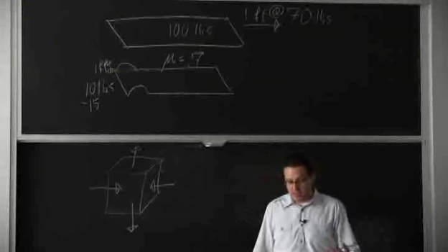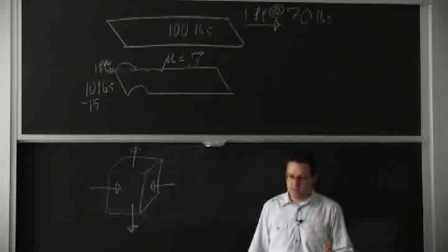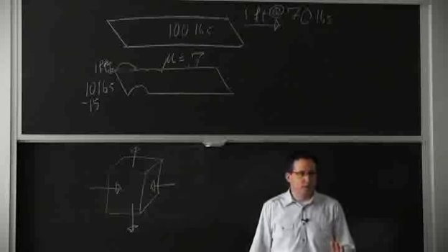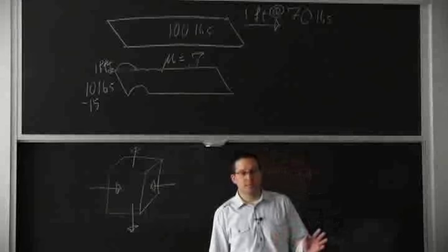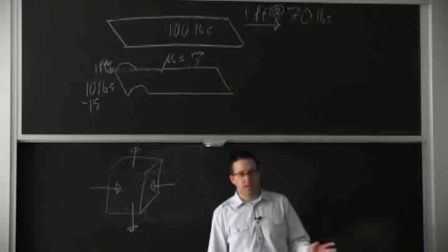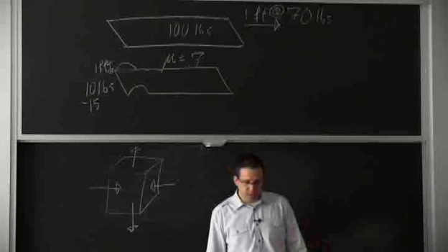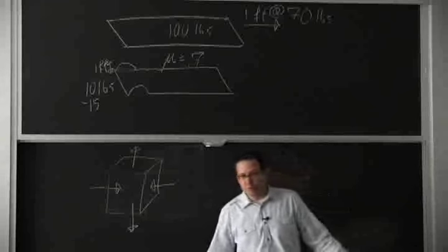And that also relates to what we talked about, where at the end of the day, we do want shear in the material for yielding. But the whole von Mises criteria and calculation approach just allows you in 3 dimensions to figure out how much shear you have as opposed to hydrostatic pressure, and am I in a yield condition or not. So that's what I'm hoping you come out of this class with,